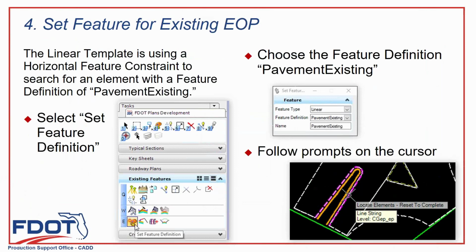So we have one existing curb template that is just like a 1/2 foot wide. It starts at the very back on the ground, goes down a foot, and then it's looking for the inside edge of the curb or the edge of pavement. But right now, it's only at a 1/2 foot. So when you first place it, it's only going to be a 1/2 foot curb all the way around there.